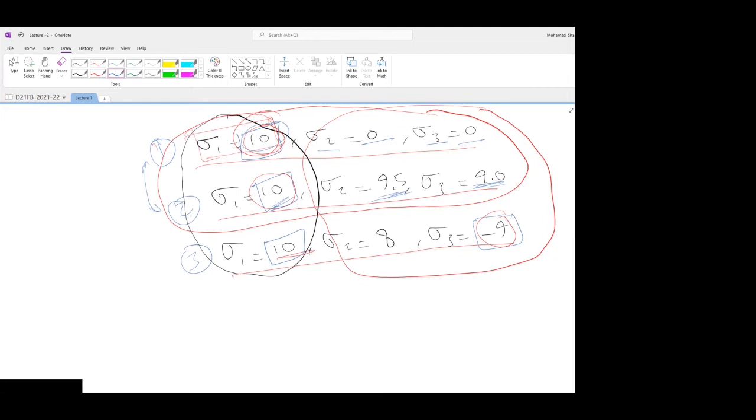Now, the stress itself, if you look into these principal stresses, we are actually projecting the stress. The entire stress is being projected into 3 directions. Now, this is why I said it is different than the forces. If you have the force, you project it into one direction. So this is the x direction, and this is the y, entirely projected in the x direction. You get the entire amount of the force active in one direction, and you know that this is what is going to affect your structure.